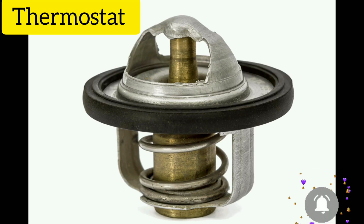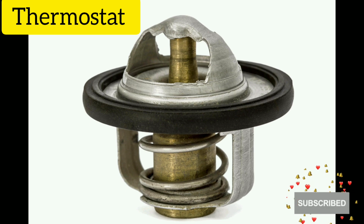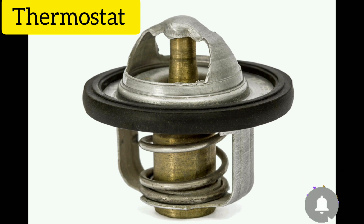This is a thermostat, and it's located on the top of an engine. Its purpose is to allow hot coolant, after the engine reaches the normal operating temperature, to be returned to the radiator for the cooling process. Its main purpose is to prevent coolant from returning to the radiator when the engine is not at normal operating temperature, and it allows coolant to be returned to the radiator for cooling when the engine is at normal operating temperature. That is what a thermostat does on an engine.